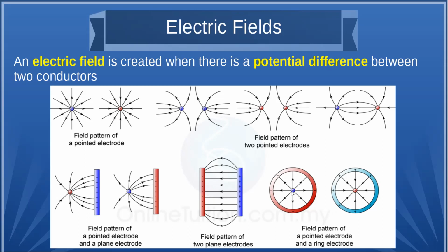In this one, assume this is a wire and you're looking end on, and centered in this conductive tube, which is how coaxial cables work. Somebody got the bright idea, instead of having two wires side by side, where if you don't, like we talked about, twist them to reduce the interference, they're susceptible to outside interference because other fields can affect it.